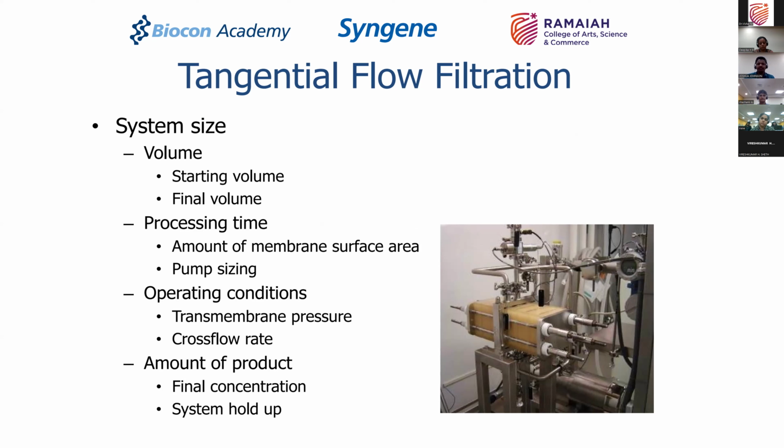What are the factors? What is the membrane MOC? What is the initial volume? What is the final volume? Are you concentrating at 10x? Are you concentrating at 5x? What is the time which is required? And therefore, what is the processing area of the membrane that you need? What are the operating conditions in terms of transmembrane pressure, temperature, etc., and what is the amount of final product